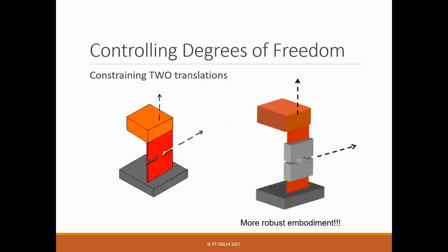In this case, the problem is that because you have reduced the section, the load carrying capacity is reduced, and then it's so easy to fail. So what you do is reinforce. You increase the thickness here. So you put an embodiment, but you still put these hinges here.